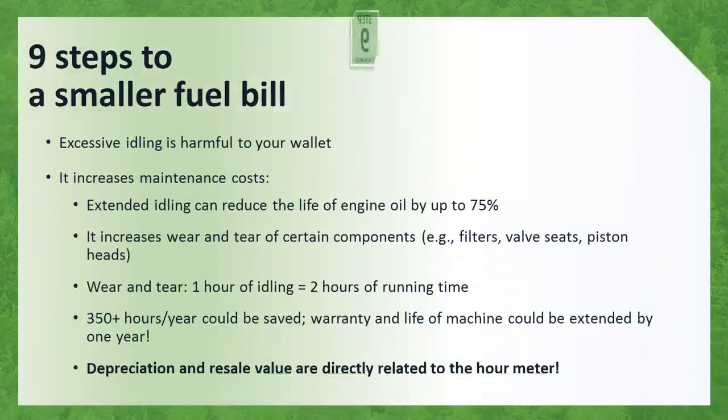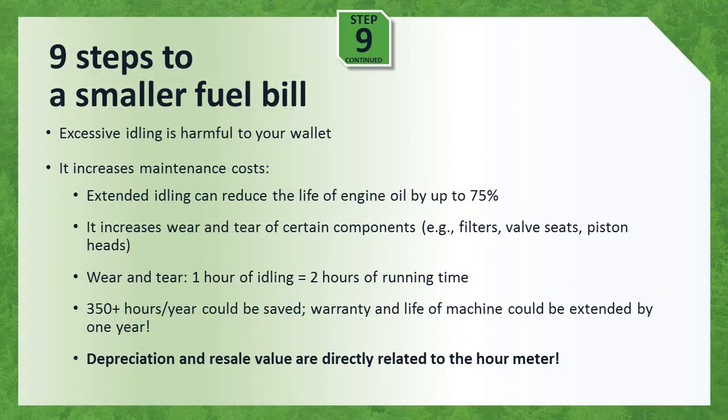Low hourly fuel consumption can be an indication of excessive idling. Excessive idling can reduce the life of engine oil by up to 75%, increase wear on mechanical components, and negatively affect maintenance schedules, depreciation, and resale value, as all are tied to the engine's operating hours.